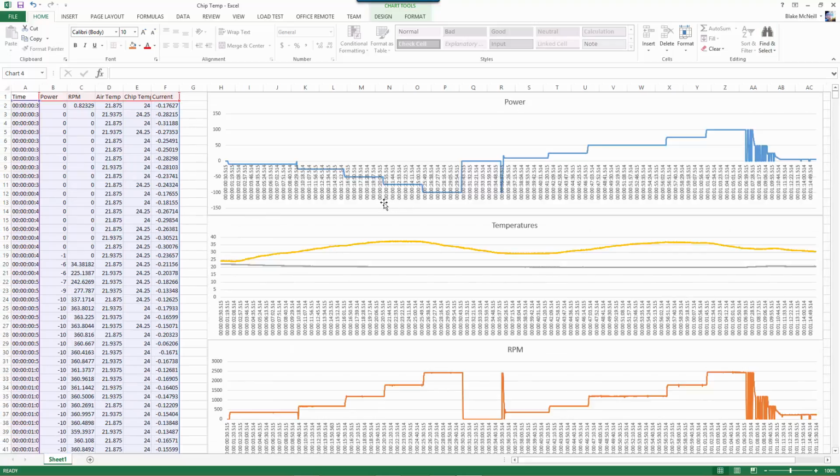One of the things that I was wanting to do was run at different power settings, forwards and backwards. So we have this negative duty cycle of 10%, and I think this was 25, 50, 75, 100%, and then I left it at 0 for a bit, and then I just did a quick pulse up to 100% power, or negative 100% power, and then I did the same thing here. I ran a 10%, 25, 50, 75, and 100% duty cycle.